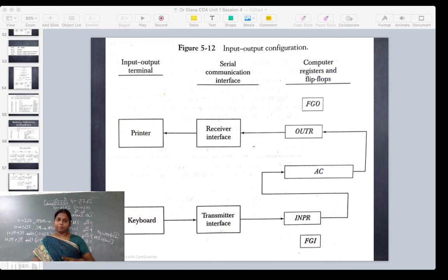This is how an interrupt works, but the interrupt cannot be raised when the computer is doing something very, very crucial, which is why we use an interrupt enable flag. When the computer is doing something very important, it disables the interrupt enable flag, putting its value to 0, so that interrupts cannot be raised at that time.